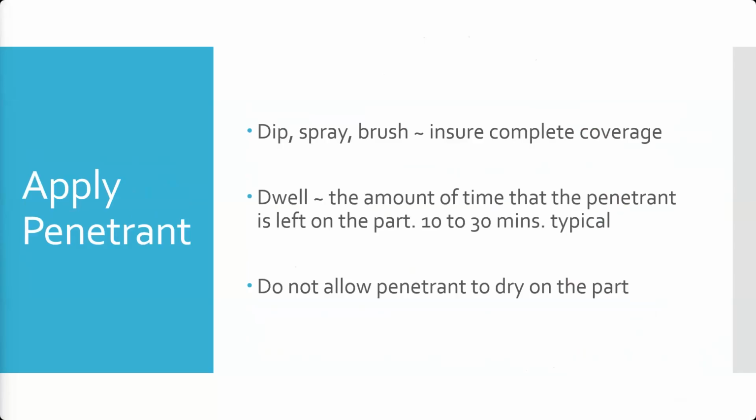If it's a small part and trying to spray it on with an aerosol is tough, you can take your penetrant from the aerosol can and spray it into a cup, one of those disposable paper soup cups or something, and then use a brush or even dip your part in it if you need to. So even though it comes in aerosol, it doesn't mean you have to apply it using aerosol. In fact, our type 1 aerosol penetrant and our liquid bath penetrant are the same penetrant, just one is in a spray can and one is in a liquid bath. So, they're multi-method.